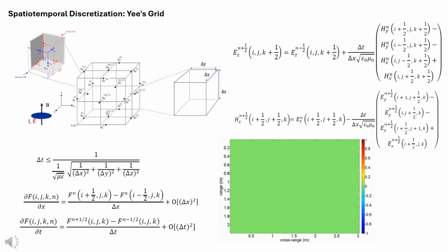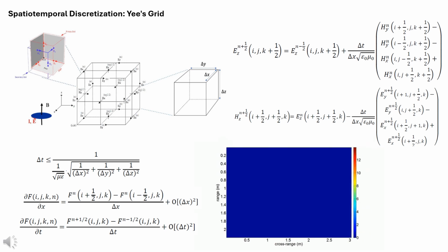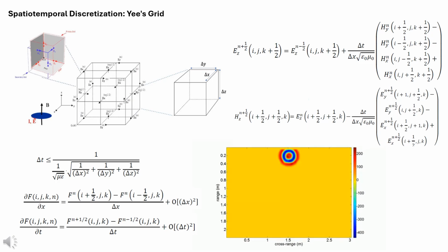By utilizing the FDTD method with careful spatial and temporal discretization, boundary condition application, and gridding strategies, we can accurately simulate electromagnetic wave propagation in complex environments such as the human head. This approach ensures that both the electric and magnetic fields are dynamically and realistically modeled, providing valuable insights into their interactions within intricate structures.